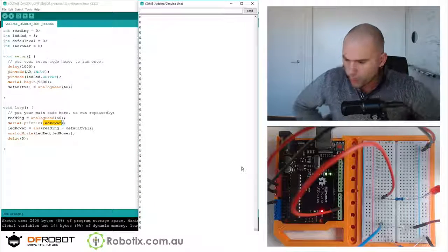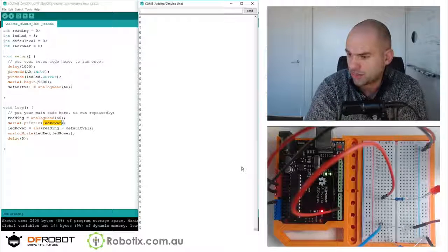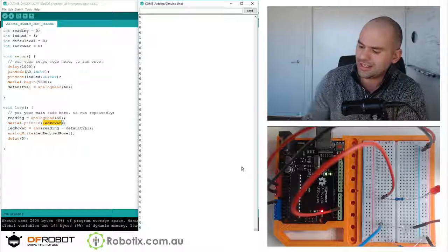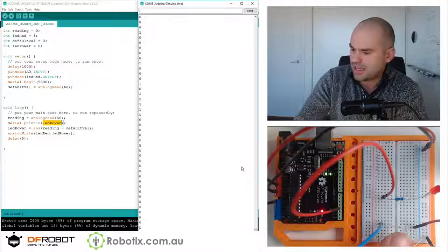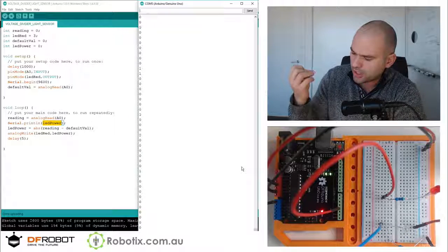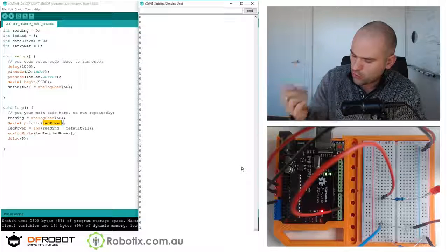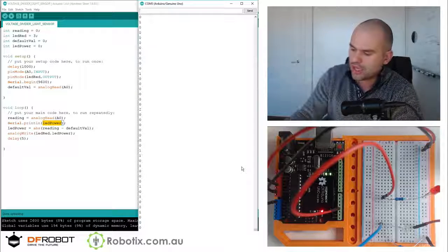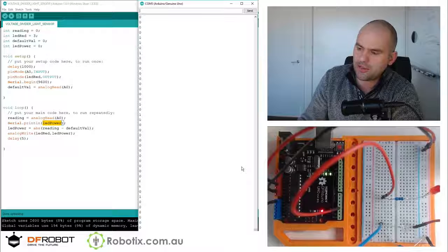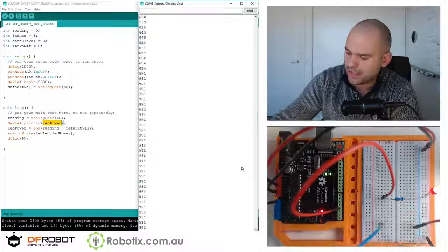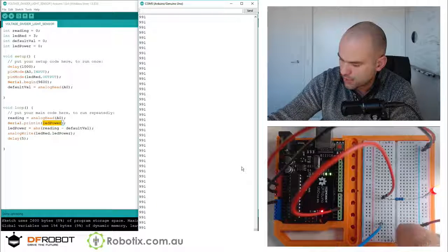So what you have here is a demonstration of how well voltage divider circuits work. All you need is something whose resistance changes in line with the variable that you want to measure. So the resistance of this photodiode changes with the amount of light that is on it. You can change the photodiode to a light-dependent resistor. Straight up, completely different sensor, works on completely different principles.